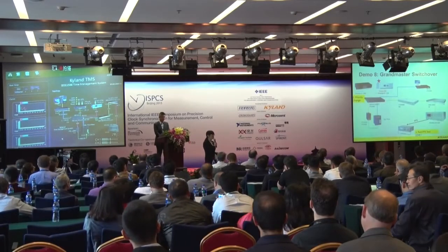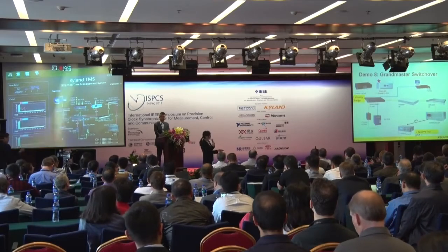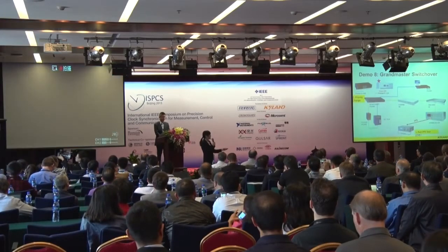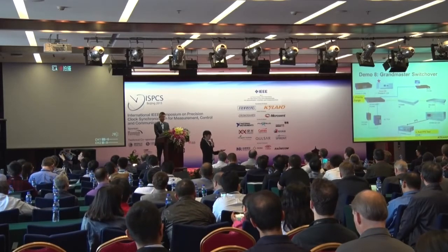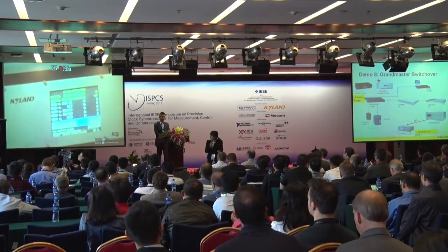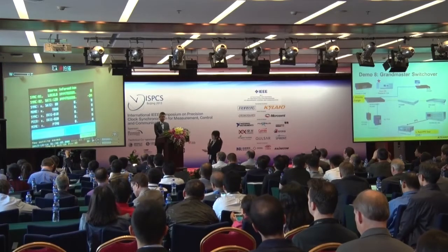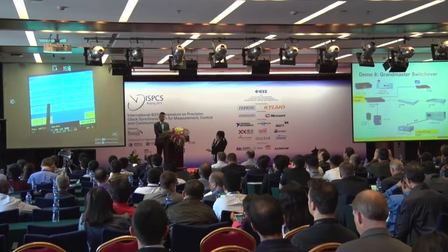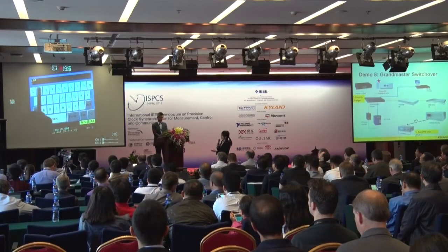Here we're going to do a switchover between different grandmasters. First, we'd like to run the PPS test through the Sifang relay, and we'd like to check the performance during this kind of grandmaster switchover. And then now we change the parameter of priority one in the Kyland clock. We change priority one from 100 to 200.